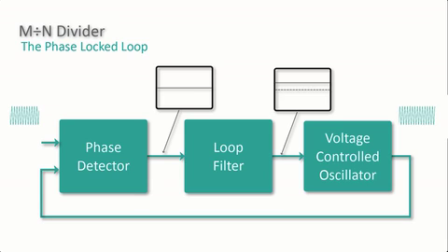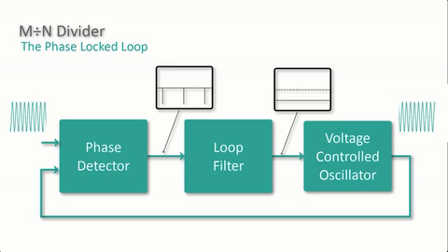Now consider the case where the input frequency begins to fall. Now the phase detector begins generating negative pulses that are rectified by the loop filter to create a negative DC level. That forces the VCO to run more slowly until, once again, the input frequency and the VCO are in phase and matched in frequency. Now the system is still stable, and the loop is still locked.